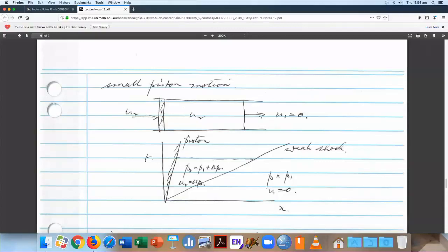So this diaphragm ruptures and I get four petals forming from a typical diaphragm crucifix. And those go back against the wall, and now I've got all of that high pressure behind moving something downstream. And it drives a very high intensity shock wave. We could understand all of that by drawing an XT diagram, and I'm not going to have time to do that.